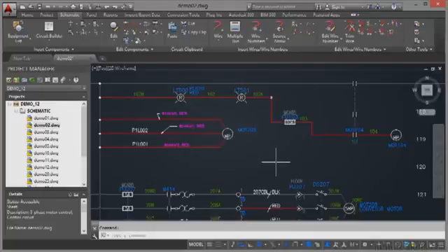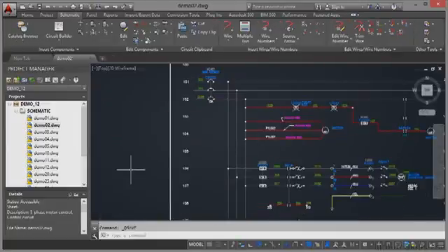There will be occasions in AutoCAD Electrical where you want to insert components from a known manufacturer's catalog file. You might be working with an existing project that uses a specific manufacturer like AB, ABB, or Bussmann, for example. Those are some typical manufacturers' catalogs that you might be using. We're still in the Demo 12 project, and I've still got drawing Demo 02 open as well. I've just done a little bit of panning and zooming though, because I want some clearance over here on the left. I'm going to be inserting a fuse in that wire length just there.